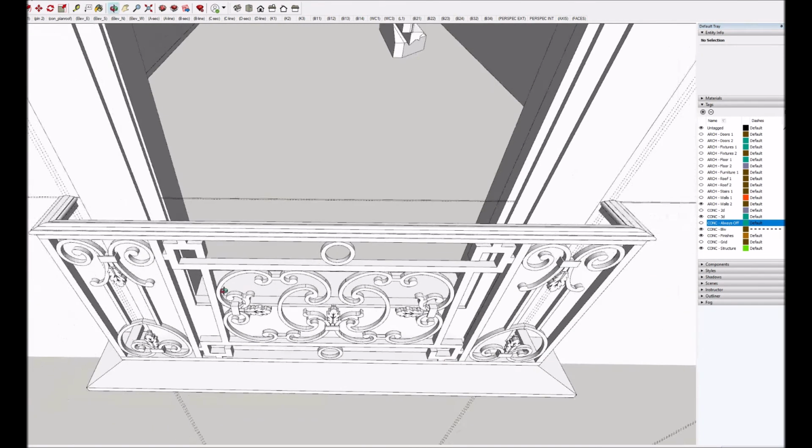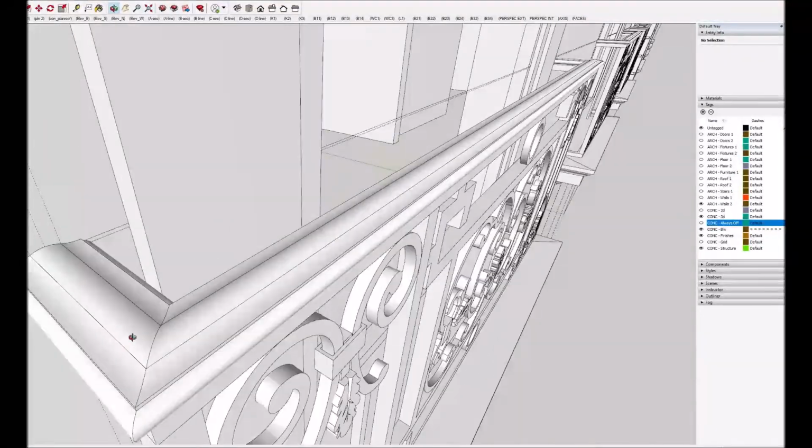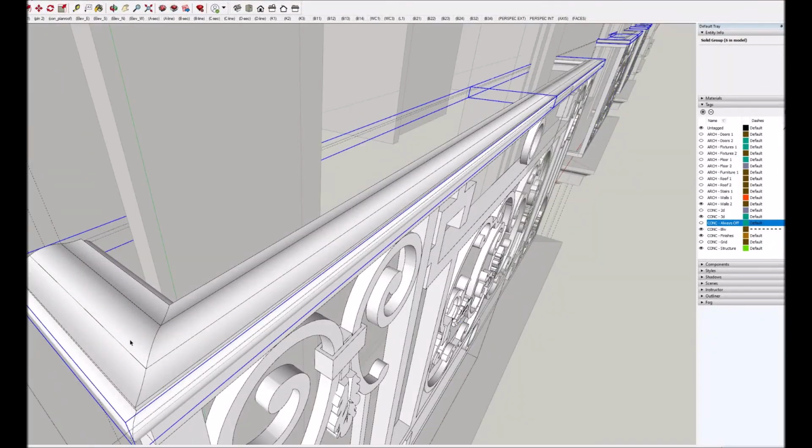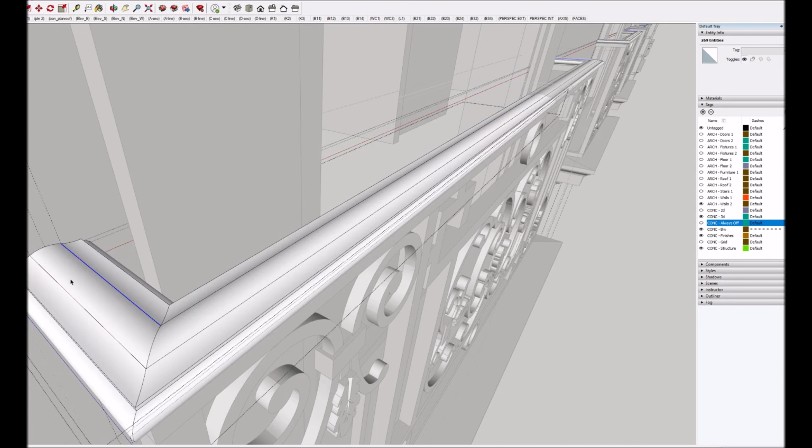And there is our cap rail. Now I'm going to also do what I just described. Here we see when I made this cap rail, the top edge was 3 curves. That means that this line and this line define the boundaries of those curves. And those are lines I'm never going to edit. I'm not going to be messing around with those. So I'm going to use the erase tool with Shift, and that will simply hide them.